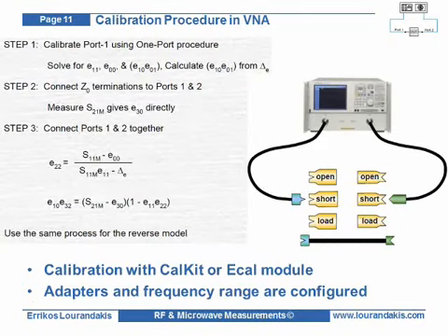In practice, the calibration routine is performed before the actual DUT measurement. A VNA calibration consists of several steps which are summarized here. The operator is prompted to connect open, short, and load standards at both network analyzer ports. Finally, a through is inserted between the two analyzer ports. At each calibration step, the corresponding error terms are calculated by measuring the well-defined calibration standards.